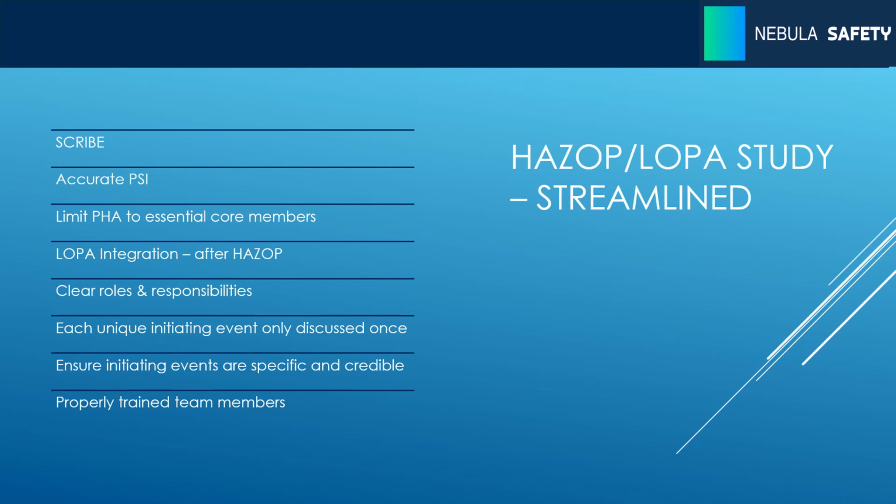somewhat different methodology. The teams often get caught up in the nuances of the different methodologies. Additionally, we will want a controls engineer in the room, and since we don't necessarily need them for the whole HAZOP process, this frees them up during the qualitative portion of the study and then brings them in for the LOPA portion of the study. It's just a better use of resources to wait until the end to conduct that LOPA with the necessary teams